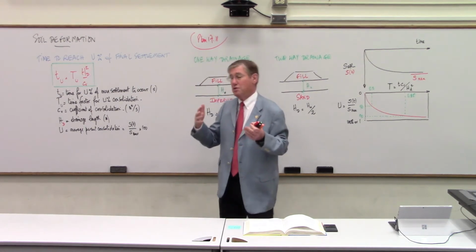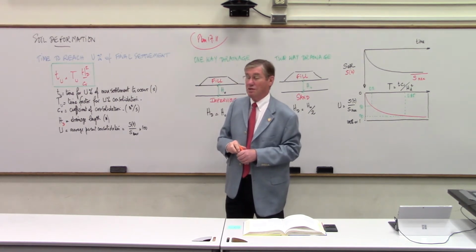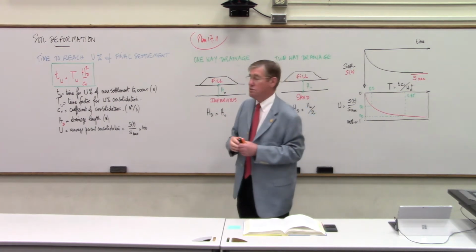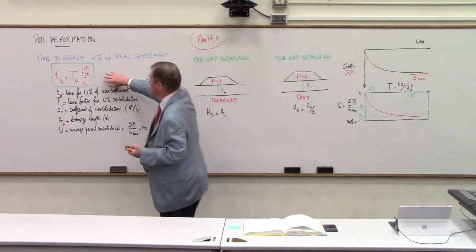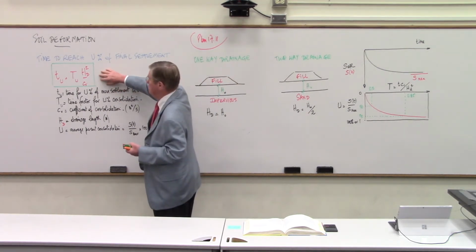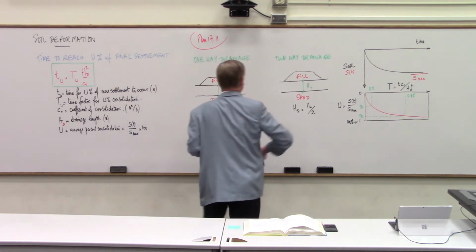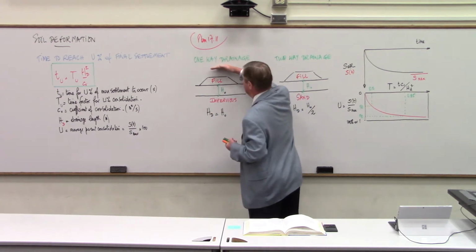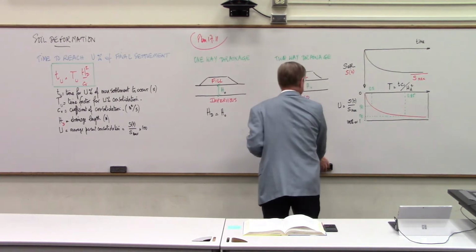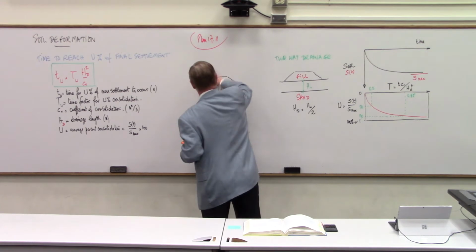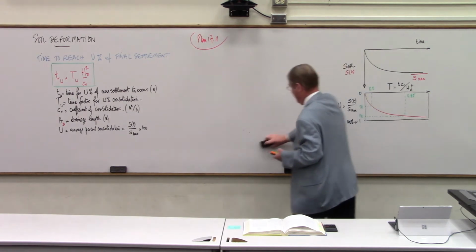Twice as high. So temptation might be, from just quick reasoning, well, it's going to take twice as long. That's wrong. The answer is, it's going to take the same time. Why? Because in here, there's nothing that says anything about the loading. In other words, whether you have a very high embankment or a very small embankment, it's going to take the same amount of time. So let me illustrate this. And that will be a question on the final in the short questions, or very, very likely.